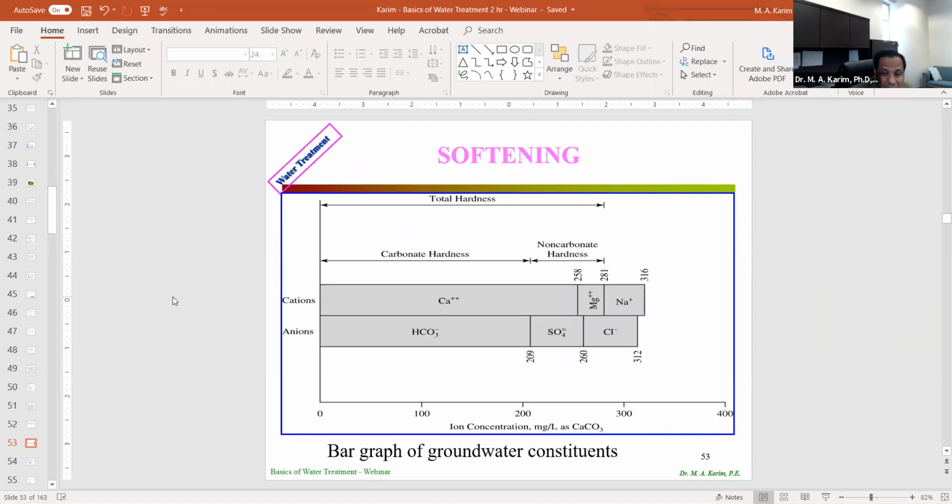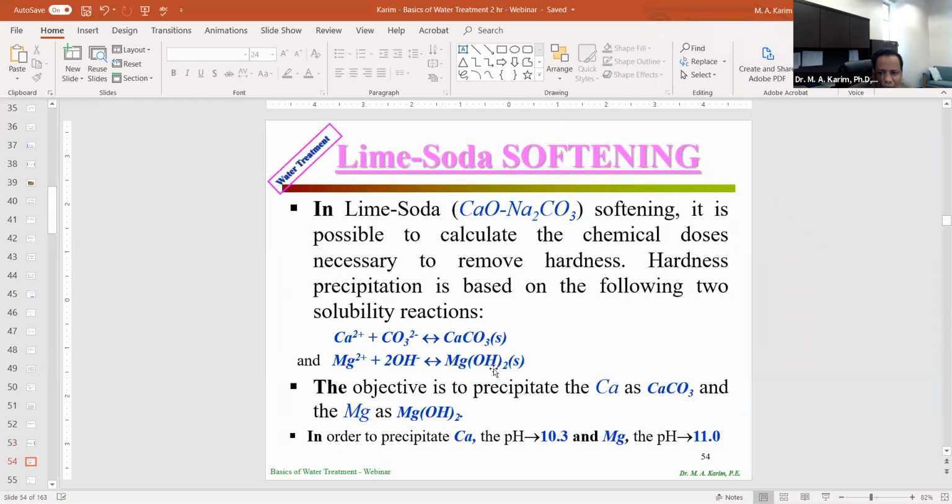So here is the way we put it together. I will show you an example where I didn't use the sodium. I just used calcium and magnesium, and there's the total. They didn't even add this one here, to show the total part of the total hardness. So then this is definitely carbonate hardness, and non-carbonate hardness would be from here to here. Because the total hardness is equal to calcium plus magnesium, or carbonate hardness plus non-carbonate hardness. So if I know this total hardness and I know this, I should be able to find the non-carbonate hardness. Okay, any questions so far?